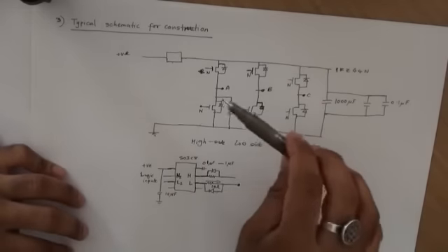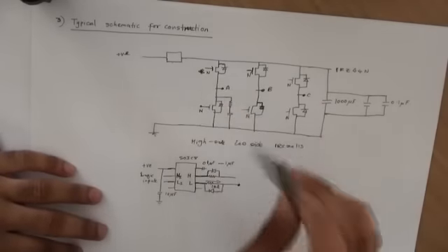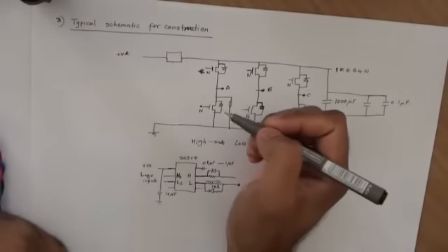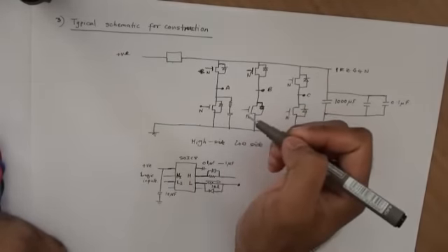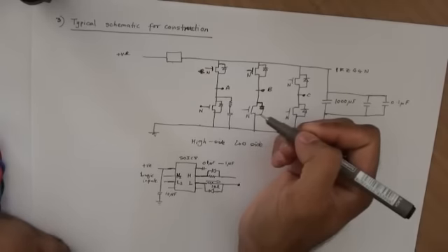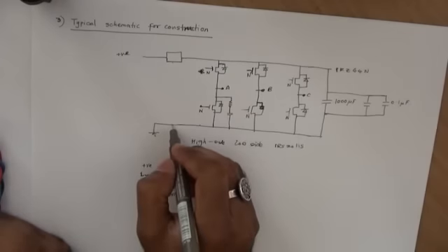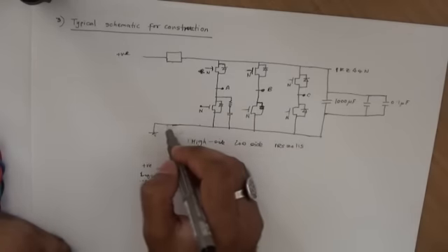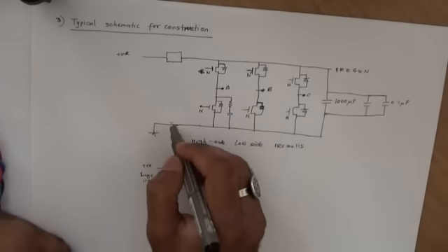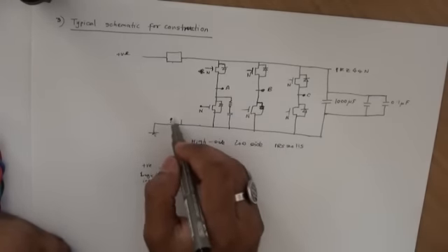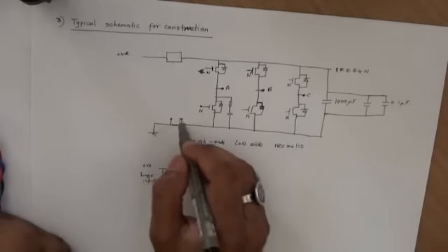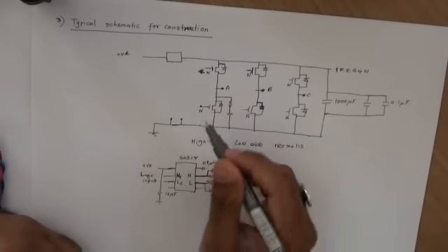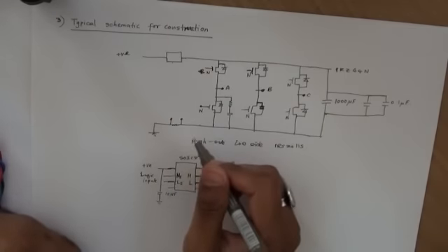Now let's talk about the current sensor. With the current sensor, in my designs, I originally had a resistor in series with the ground. Basically the idea is you put a resistor in series and you look at the voltage drop across the resistor to work out essentially the current flowing through the resistor. There are some potential disadvantages in doing that.